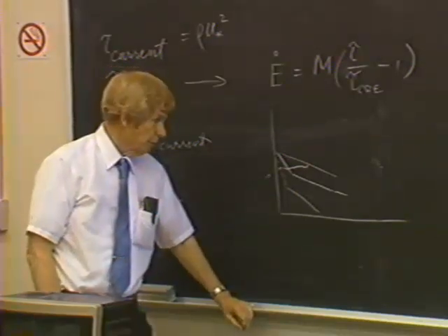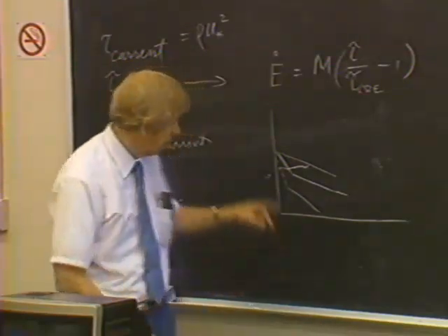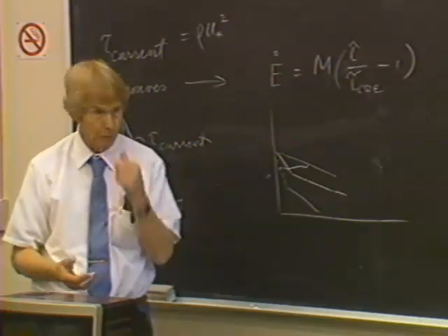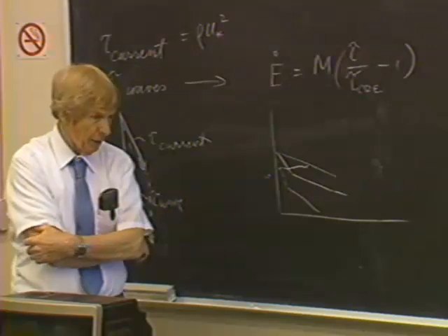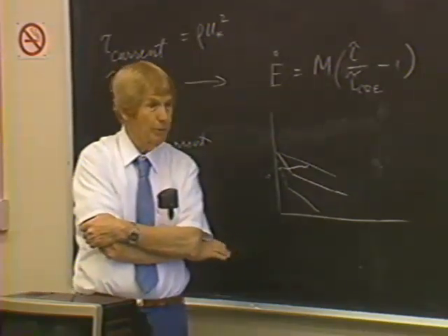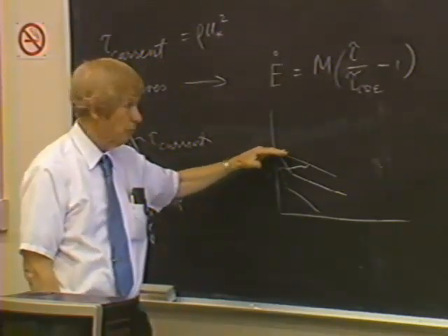So typically what happens is that if the material is freshly deposited so that it has some kind of a profile like this, then it's easily resuspended by bulk erosion. If there's a long time between the time it's deposited and the time it's subject to wave action, then it isn't easily suspended by erosion, and a different process takes place.